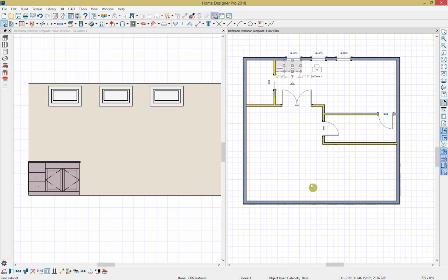Next, I'd like to create a copy of this same exact smaller 18-inch wide cabinet that we created earlier. The copy tool can be found in your Edit toolbar. I'll copy this object, and you'll see that my mouse will appear with the ability to paste. If I paste this object, it will paste right by it. I'd now like to place one more base cabinet, and then I'll show a tool to reflect these cabinets about the main base cabinet. I'll select the base cabinet and place it here in my floor plan, and I'll double click to open the object.